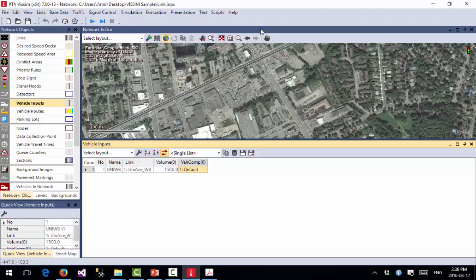The light signal durations, like the phase and cycle durations of the signals. So basically, we want to see where we have signal heads, what the phases are, and what the timing of the signal is. What else do we need? So now we have the layout, lanes, turning movements. We have the signal heads, phases, timings. What else?